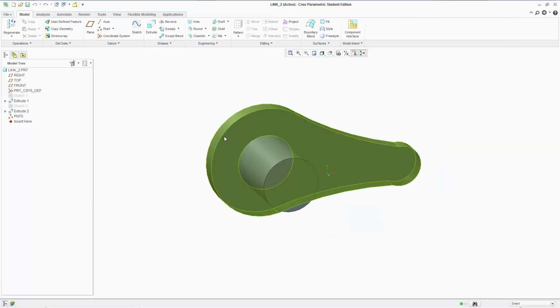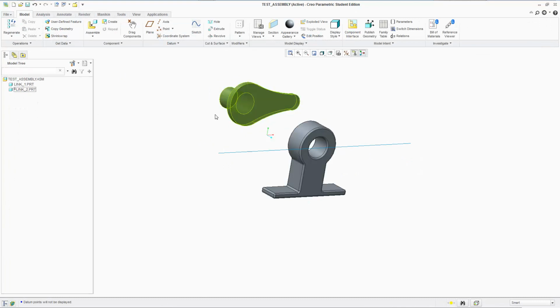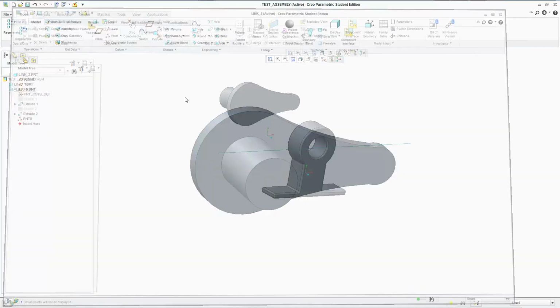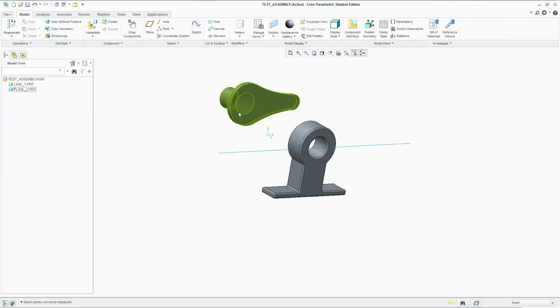And you can make a point here, you can save it and make changes accordingly, and they're going to be reflected upon the part that you have open in the assembly. So any changes you make when you open right here, you right click and open, and you make changes and you save it, they're gonna be made automatically here. You just gotta hit the refresh button right here.